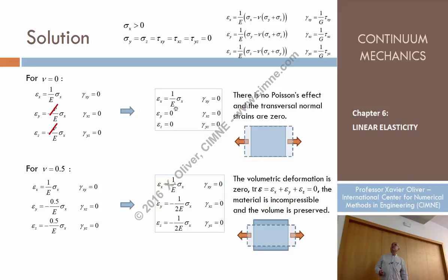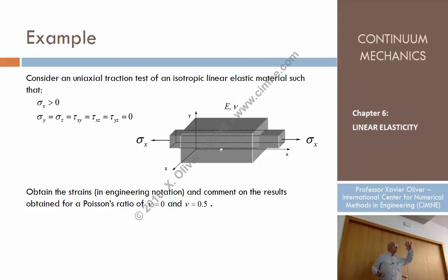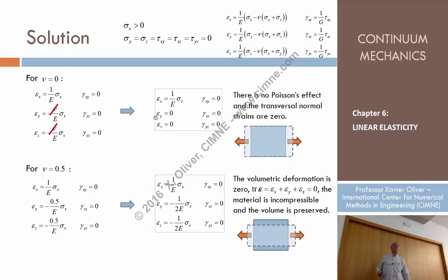So there will be an elongation in direction x, an extension, but then in the directions y and z, in the other directions, there will be no contraction, no elongation. You see? Because epsilon y and epsilon z are 0. And also the shear strains will be 0, so the angles won't be modified. So typically, in that limit case, the strain will be just in the one direction, and so as for the corresponding deformation. Okay? No contraction of the cross-section due to this stretching.